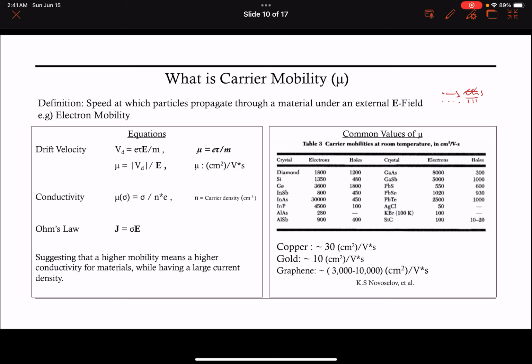And in graphene, showing this ambipolar field effect, which I said I was going to talk about later, I'll mention it right now. Now, this ambipolar field effect is pretty much the switching of carrier types. And we will see in a graph shortly that the carrier type actually corresponds to which side of the resistance graph and which side of the conductivity graph you reside in. So there's holes, positive charge carriers, and then electrons, the basic ones being negatively charged. And as you can see here by Ohm's law, higher conductivity materials will have a large current density. So that means we're pushing electrons at rapid speed.